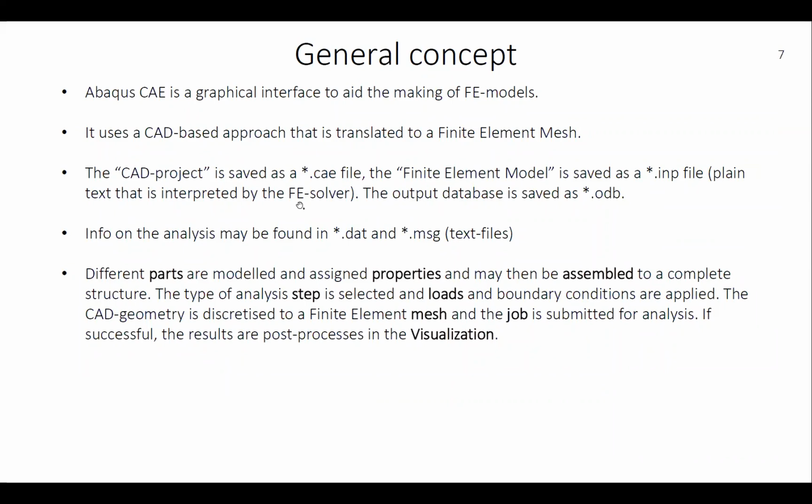And you have a dat file and a message file, which include some analysis or log of how the analysis is proceeding. If there are any error or warning messages, you will find them in either the dat file or the message file.